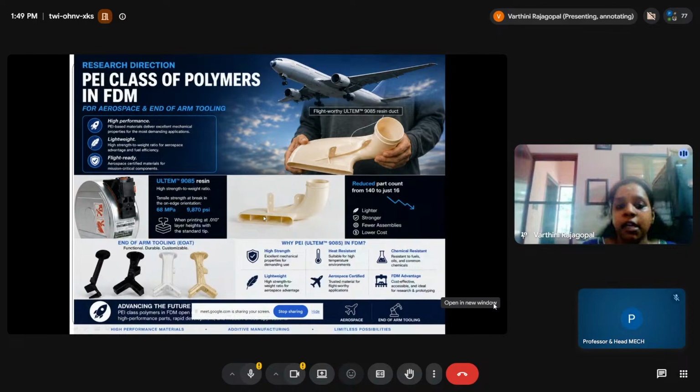So here, instead of having a nozzle, what they have done is they have replaced the nozzle with a cartridge, a cylinder portion, and the end portion of the cylinder has a syringe, right? You will be using the hydroxyapatite and calcium composition held in this cylinder, and over the petri dish, you will be moving the syringe to create the required profile. So this is how the FDM will be modified to make it a 3D bioplotter. So this is actually the bioplotter.